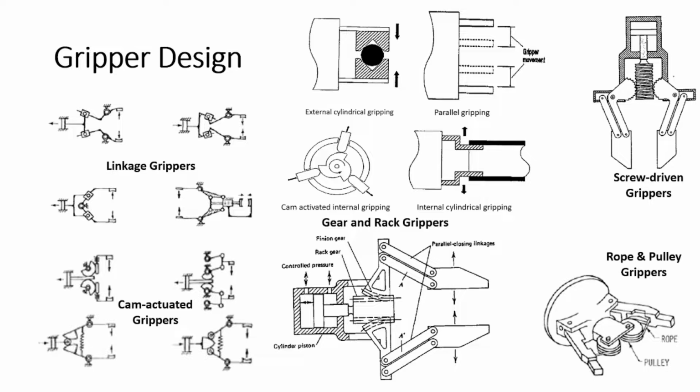So in order to keep that part in place, how much force is required by the motor? That's the inertia moment you need to know. So in order to control the robot, we have different types of grippers. In this gripper, we specifically used the linkage mechanism.